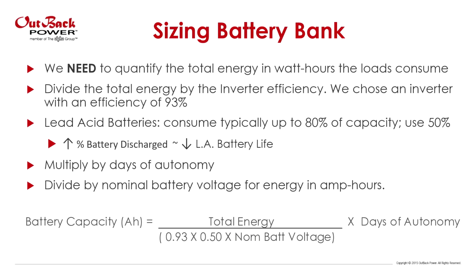All right, so now we are going to size the battery bank. So we have a total energy from our step 1 from our load calculation. We did this by estimating what the loads' power requirements are, and how long they are on for in a particular day. Remember, energy is in watt hours or amp hours. There will be some efficiency loss in the system, so the batteries will need a little more energy than the loads require, since some of it will be lost through heat along the way.